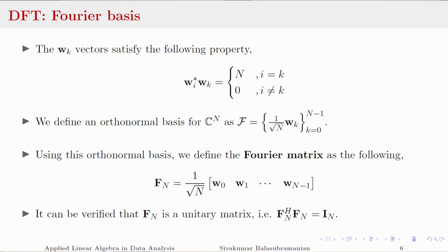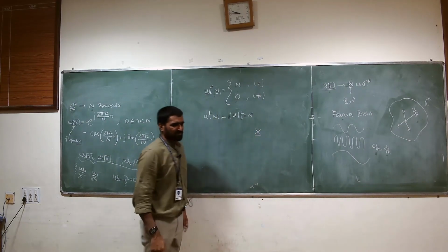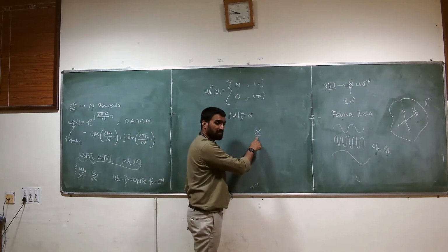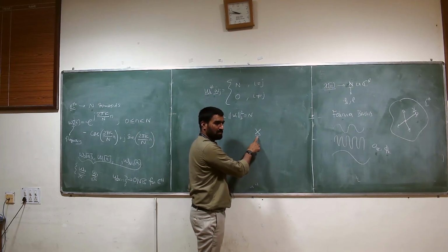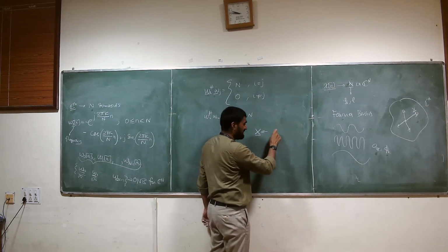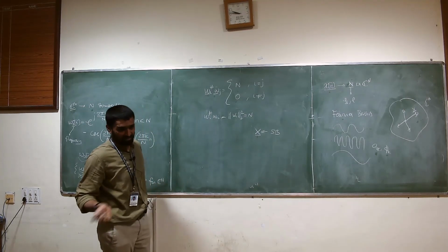and I have my original time domain signal, x, what basis is this represented in? My original time domain signal is in the standard basis, right? And the standard basis corresponds to time shifted impulses.